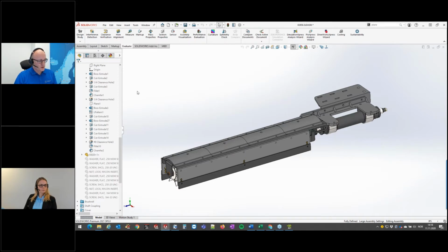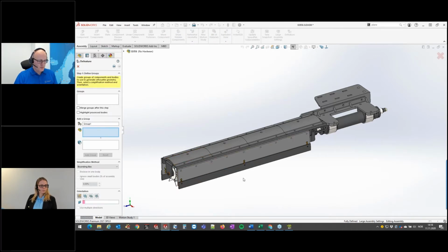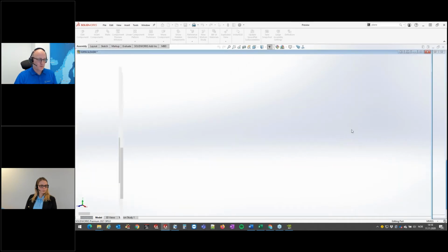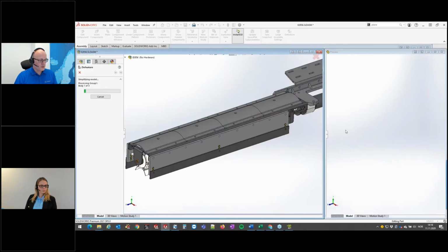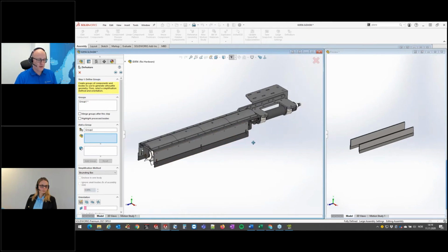To show you a little bit about that, I'll make a quick defeatured version. Making the defeatured component itself is not really new, so I'll race through this. If you have used defeature, you probably know that when you start selecting the different simplifying rules on your subassembly, you get the preview on the right here, and the full version of the assembly on the left.